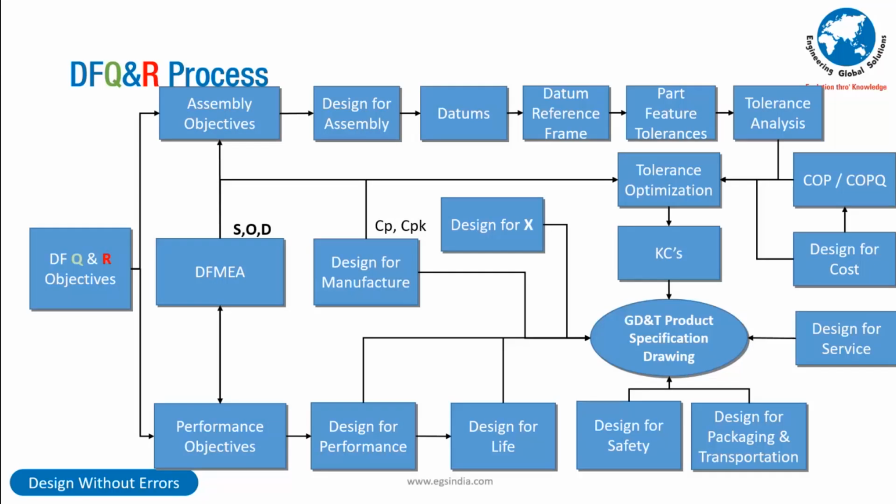While on the other side, we look at the assembly objectives and look at the design for assembly, with the basis of that forming the datums getting enumerated and the datum reference frame coming into picture, and the part feature tolerances getting enumerated, and using that to perform the tolerance stack-up analysis.